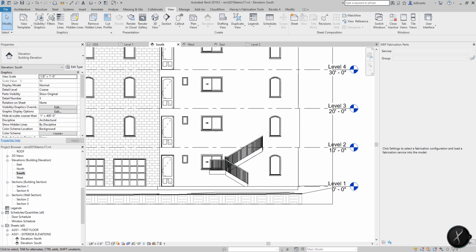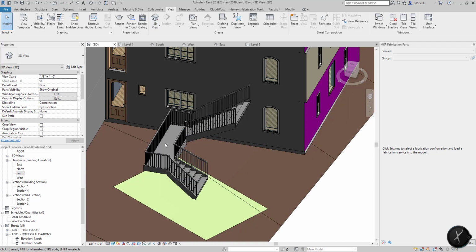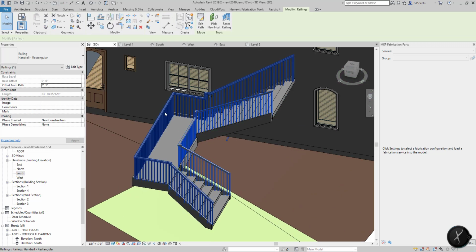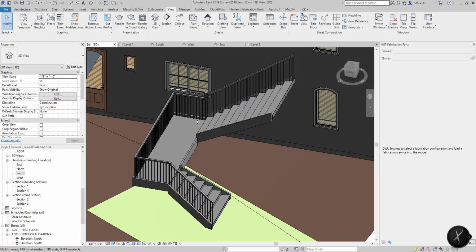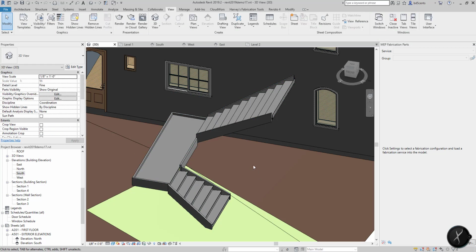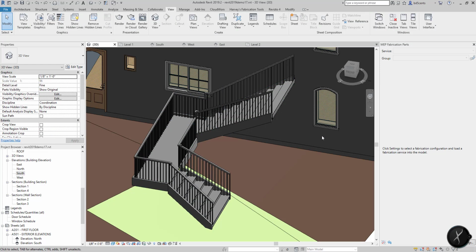The railing can be changed or deleted by section. So right here, there's a series of different sections. If I view it in 3D, you'll notice there's an interior section and an exterior section. You could delete these, but I don't advise doing that. So let's undo that twice.